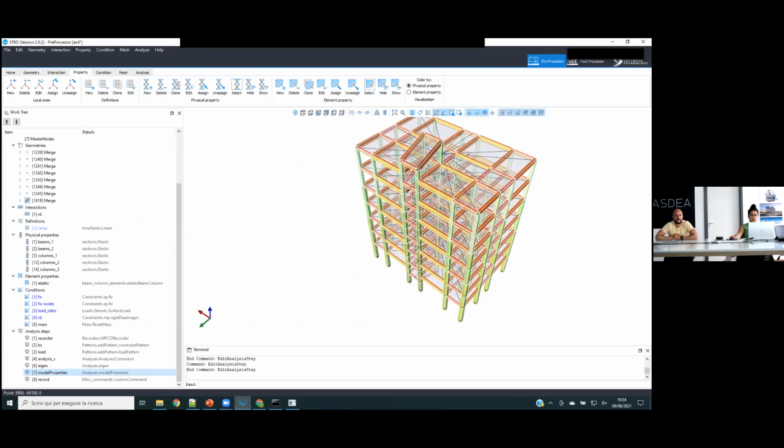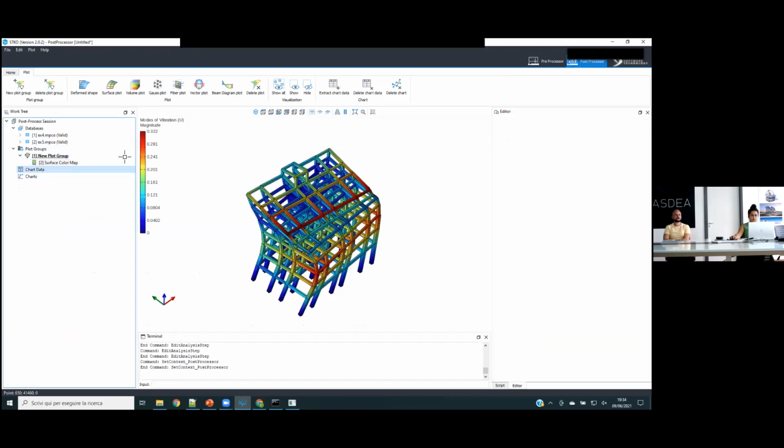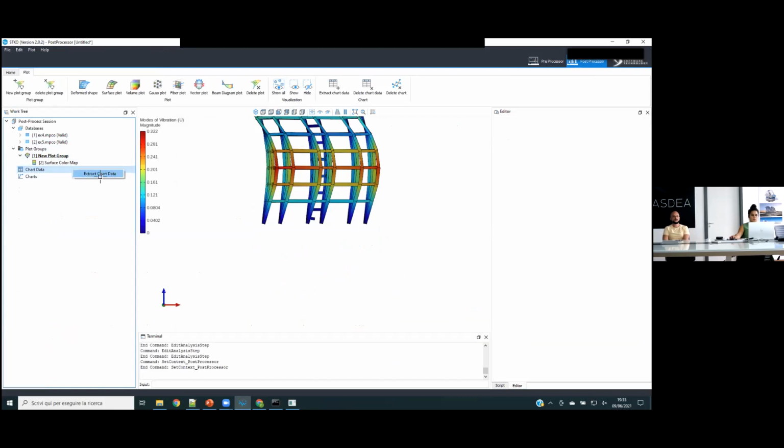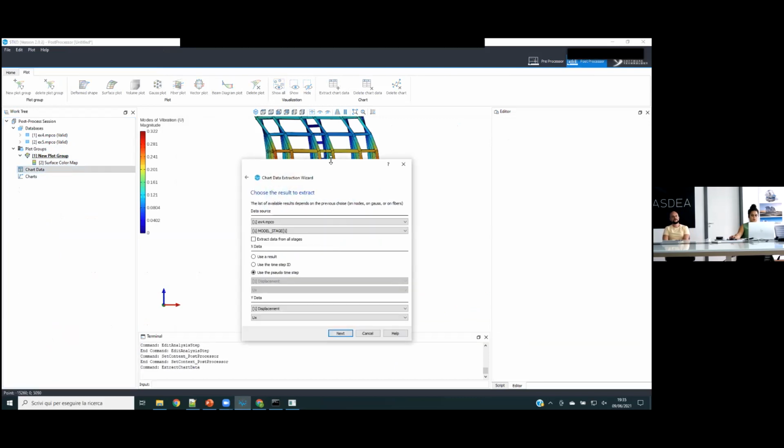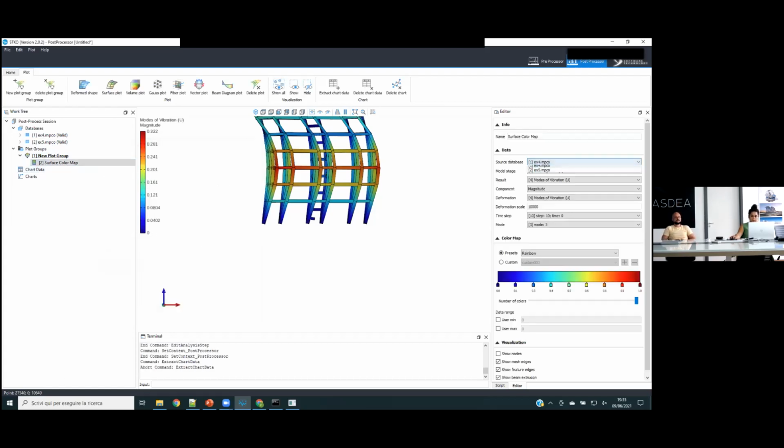You also asked about the base shear, and that's just a simple extraction of a result. You can extract the result as Francesca showed before, or using the monitor, so you can grab the base shear. You can just go here and select the nodes. Now in this case, we don't have horizontal forces in this model, so I can choose the other one. For model stage 2, I did a pushover. But you need to change the plot from this model to the other one.